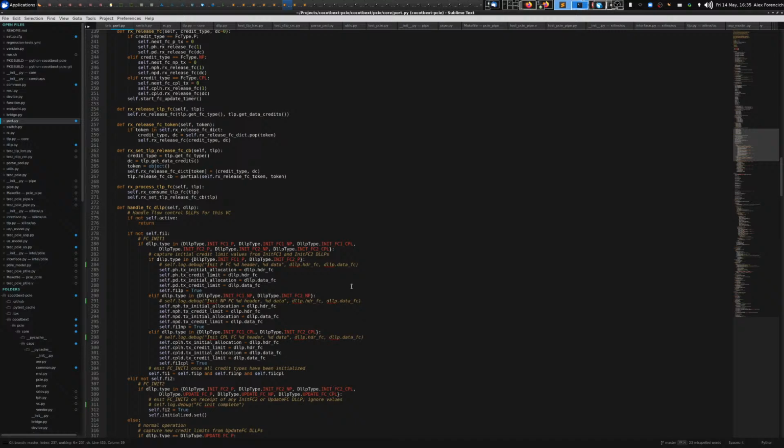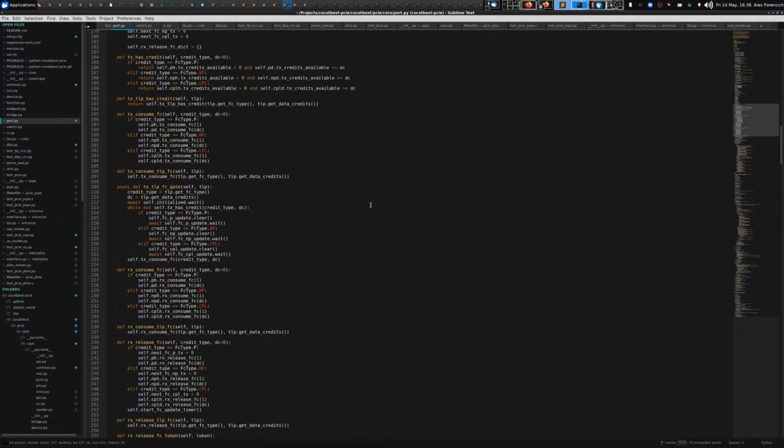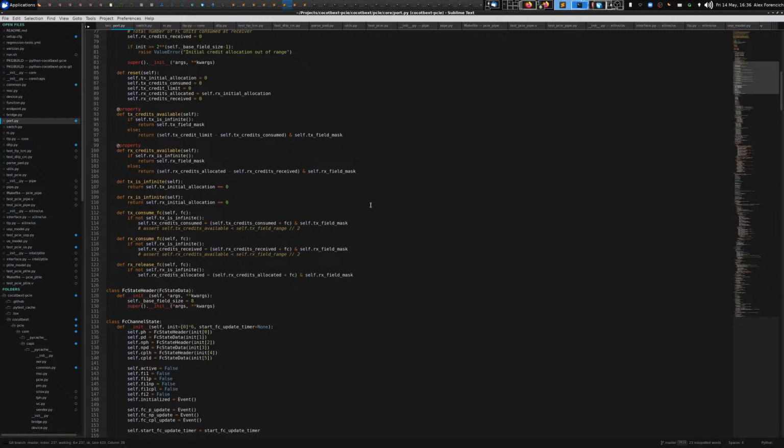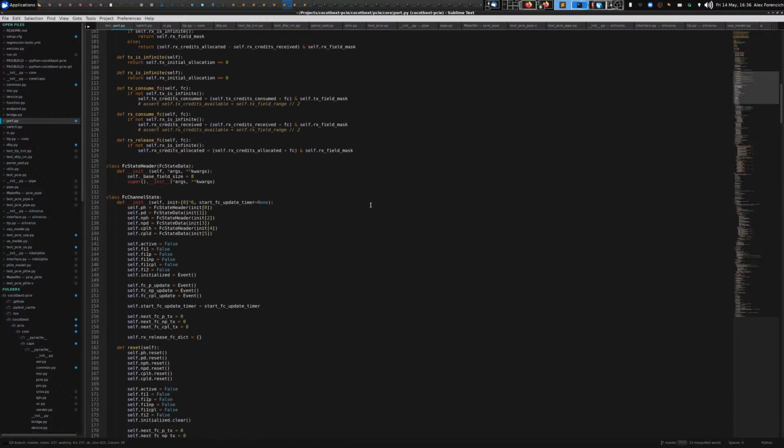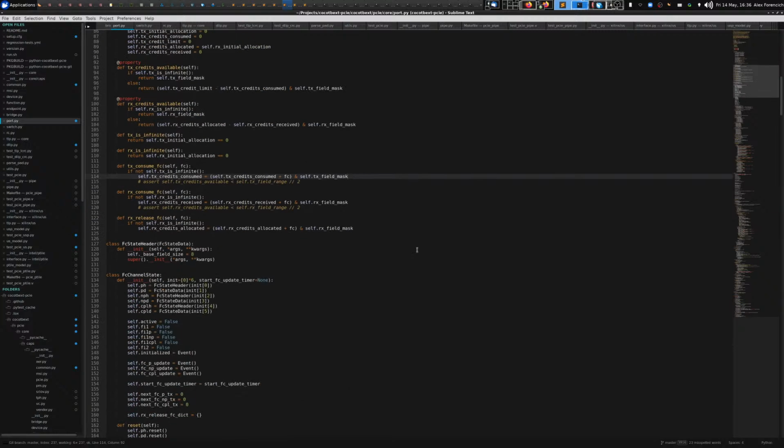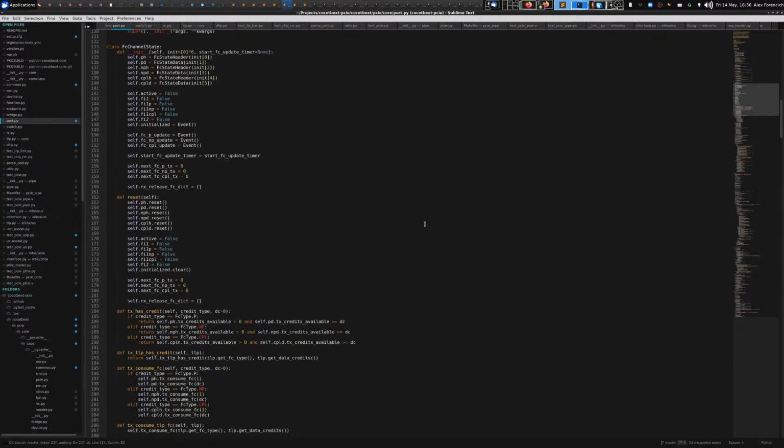But if I implement the PIPE interface, then that means you would be able to use this stack with a commercial PCI Express IP core, or with the actual models that Xilinx and Intel provide for their IP cores, because all those are simulated with the PIPE interface as the host interface. So at some point I will circle back and get that working. A couple of asserts here, why those are commented out, whatever.